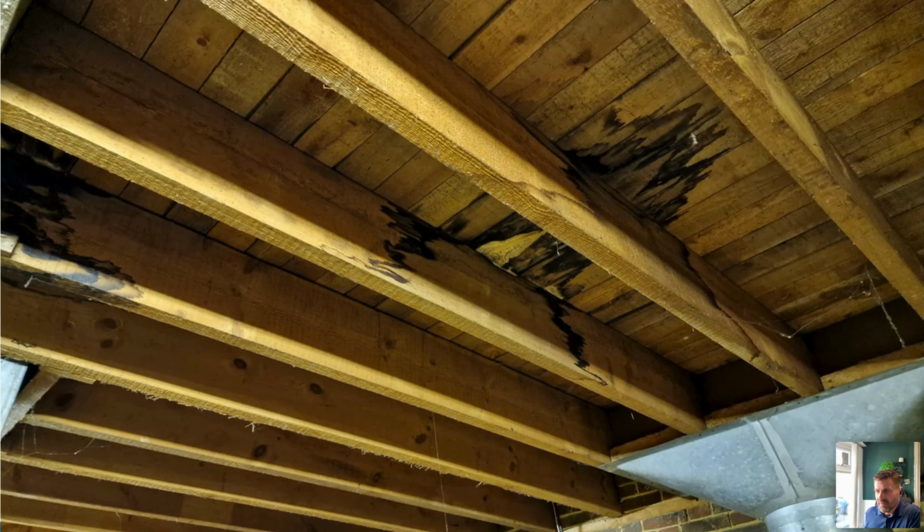So, like I say, when you're doing a core sample, it's not uncommon to come across this and see that there's a nailed layer in place that you can easily remove. Like I've done in this image, it's more likely that you're going to identify a timber boarded deck from the bottom, because if you're doing core samples from the top, all you're going to see is joints and planks.